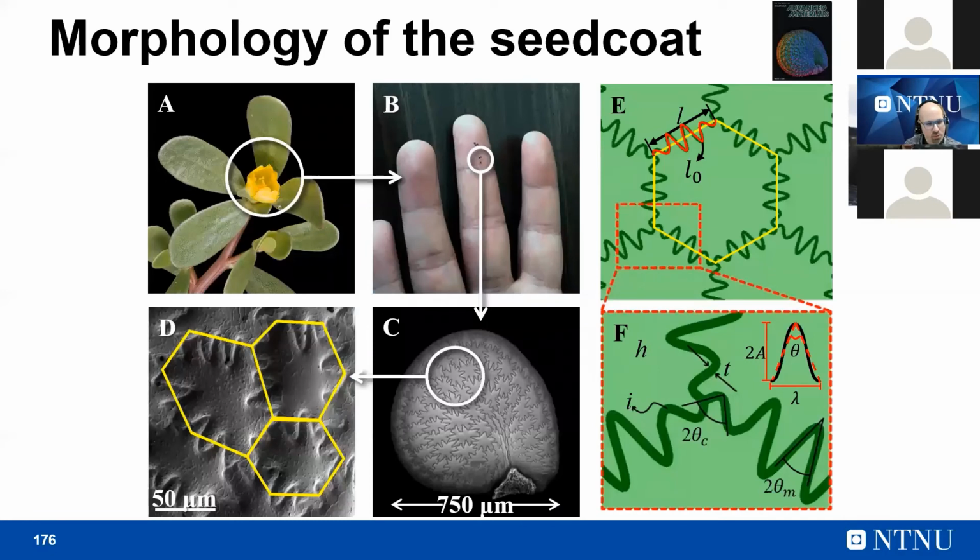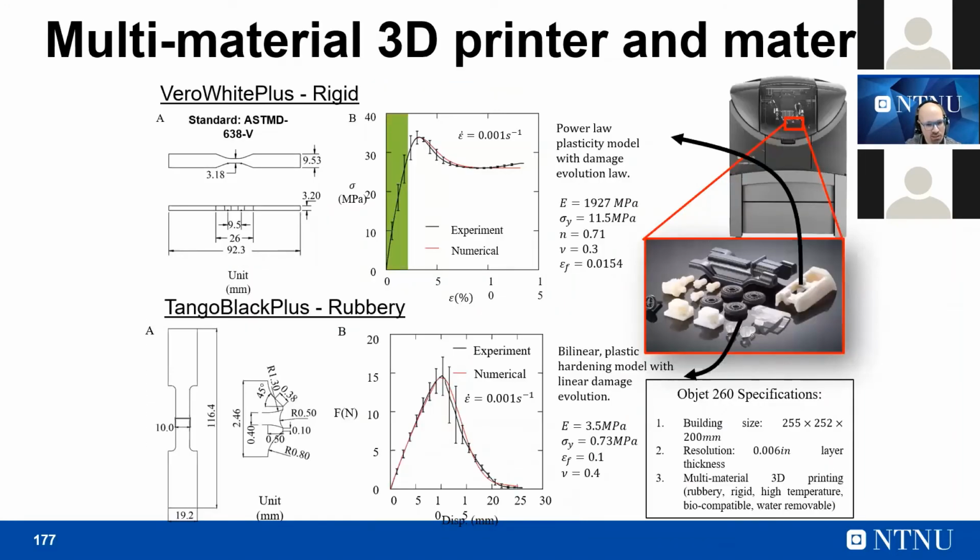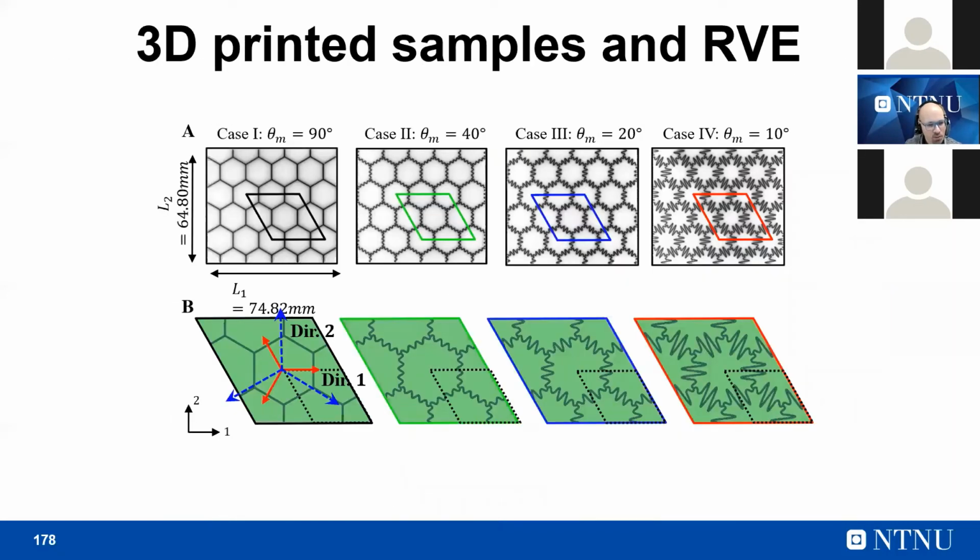And after that, I want to show you some fun topics that I'm developing right now, mainly thanks to this guy, a professor who came from the US and is now in my team at NTNU, Professor Chao Gao. We are working on additive manufacturing, and specifically on interlocked behavior that mimics nature in additive components. What is very interesting is that in different kinds of natural structures, you can find these interlocking mechanisms that increase the fracture toughness, but also the fatigue life of a component. And with current additive manufacturing techniques, we are able to print these interlocking structures properly, and to estimate the advantages we have in terms of fracture toughness and fatigue strength. So we did several studies on this, and we compared different kinds of interlocking between materials.